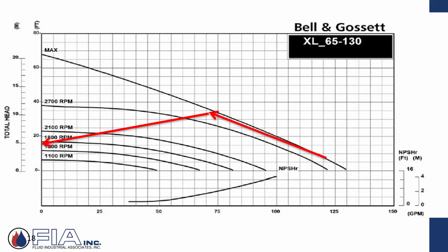So here's my curve, just from a visual, and I can operate anywhere in between, depending on the application. But what I was trying to highlight here is whatever that maximum flow and that pressure drop is, whether it's 20, 25, 30, 35, 40. So somewhere around 35 feet of head or whatever. And if you were in proportional pressure, you'd cut it in half and say, hey, I can go from 35 feet down to 17 or 16, 17 feet of head.